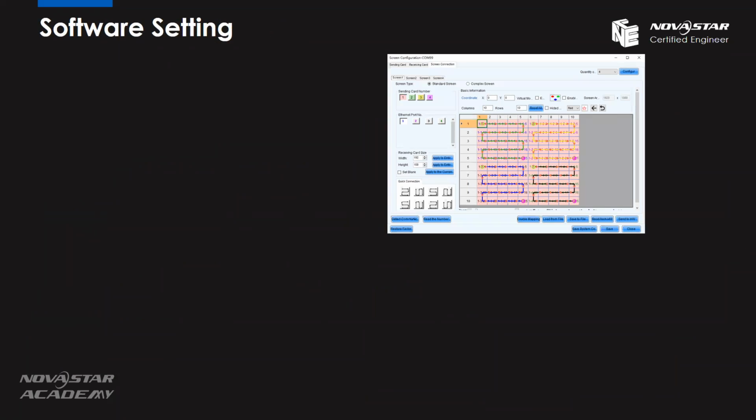At the fourth course, they told us if we have multiple screens, we need to create more than one screen. So in the screen connection interface, the quantity of the screen here, we should select 4, because now we use 4 M-Control 660 to load 4 parts of the screen. So we need to create 4 screens in the software. Now in this interface, you have 4 tabs: screen 1, screen 2, screen 3, screen 4.